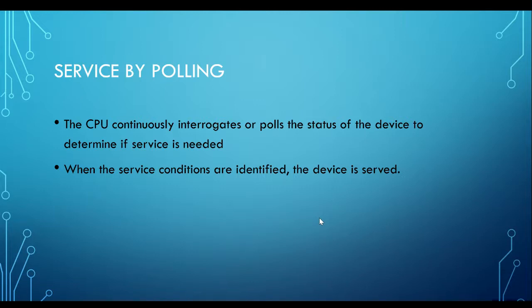And what is a requirement for polling? You need to have hardware flags. Okay, hardware flags. Okay, let's say for example, there must be 1 bit in the register that allows you to check the status. If there's new information, that flag will change its value, toggle or whatever. All right. Now some of this polling system involves detecting toggle, detecting a reset, or detecting a set.